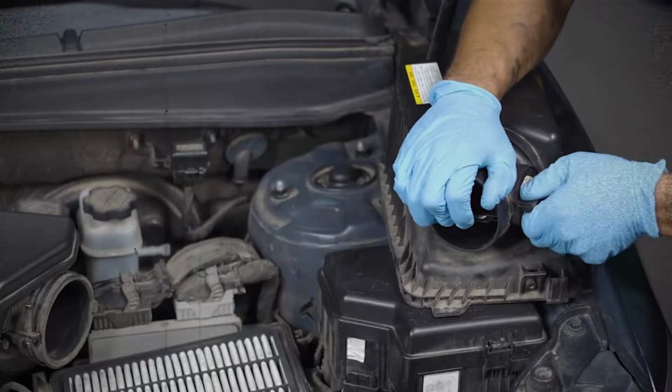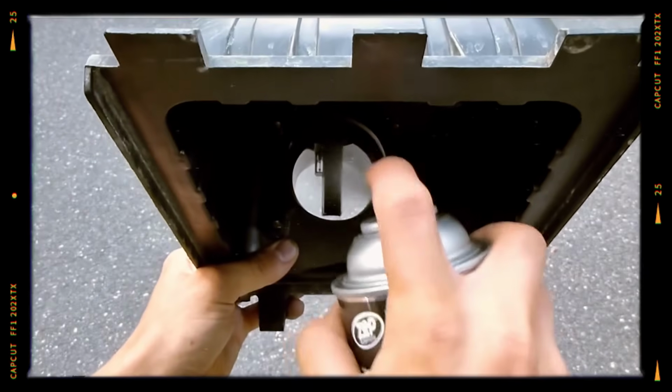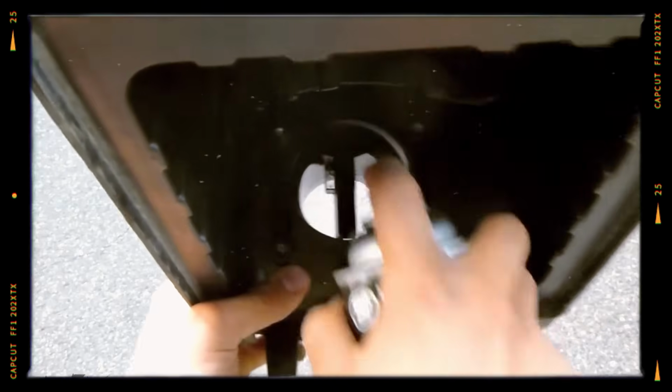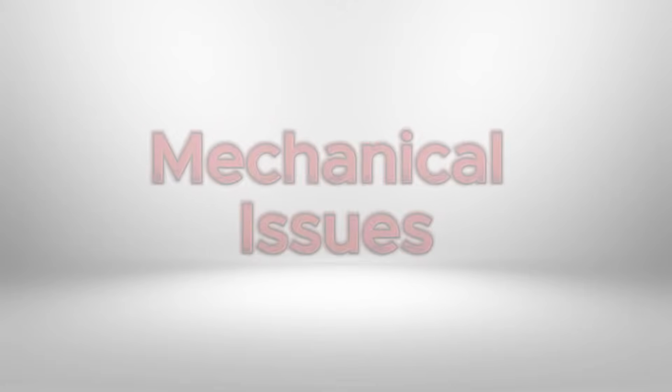Fortunately, this problem can often be solved with a simple cleaning using a dedicated MAF sensor cleaner. But it's crucial never to use harsh solvents or compressed air, as they can permanently damage the sensor element.